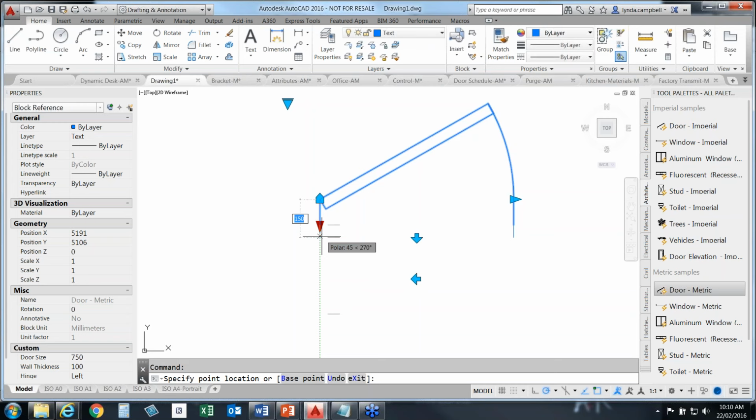For example, those doors that are now available, those doors that your client has specified they want to use. What we're used to with that little dialog box where the 100 and the 150 is when it's highlighted like that, we're used to being able to edit that. In this case, you're not able to. Those are specific values. So if I typed in 300 there, for example, it would simply jump to the closest value. Those are the only three values I can use for the wall thickness.